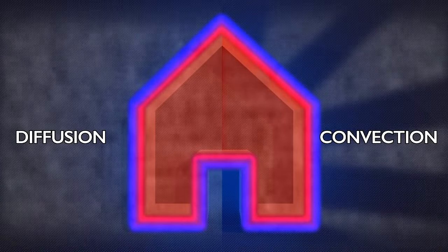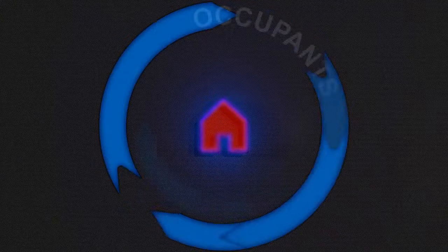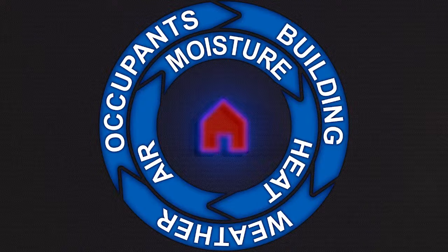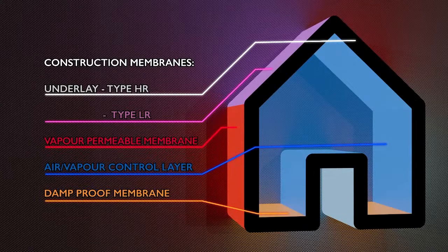To develop an effective strategy to manage the moisture risks, we need to assess how heat, air and moisture movements interact. This in turn requires a thorough assessment of the building fabric, the environmental conditions and the building uses. Once we have this, we can begin to look at optimising the materials used to reduce the level of risk, and construction membranes can play an important role in this process.